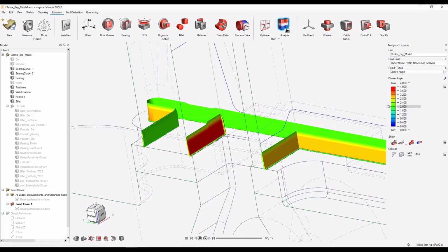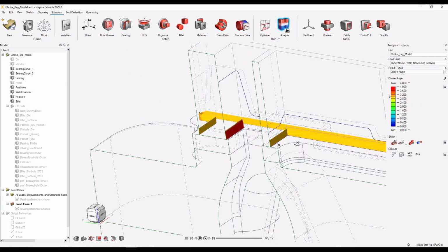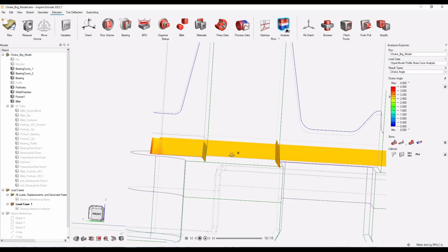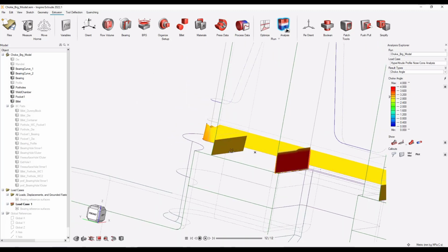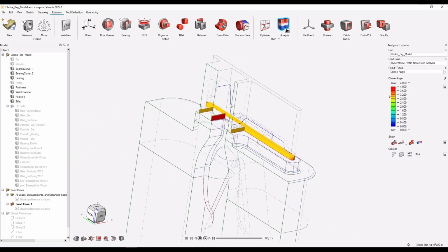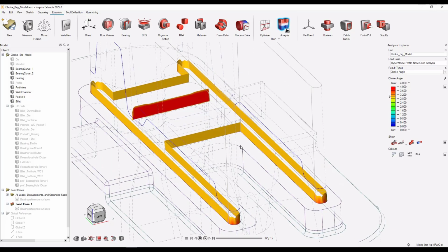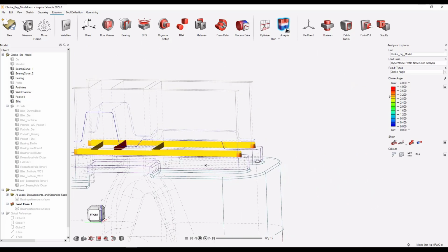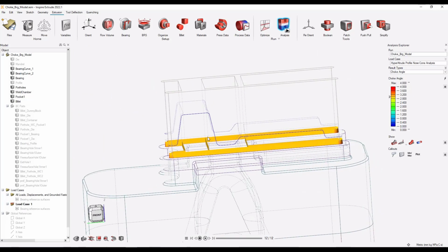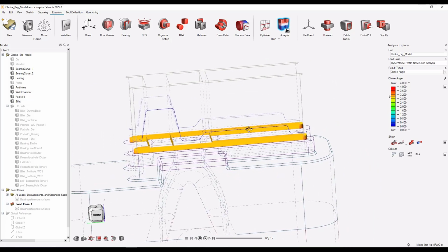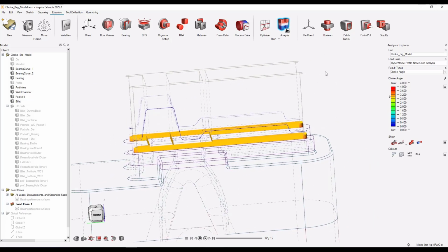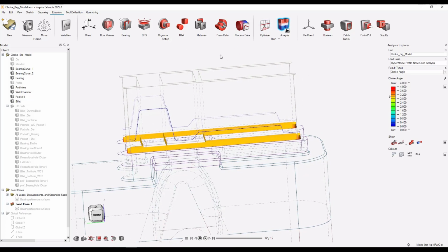Let's try changing it to, let's say, 3 degrees. So these are the choke angles with 3 degrees, and this is the choke angle with 4 degrees, that you can see over here. If I just switch on this, you can see it has detected the choke angle properly. This way you can quickly check the choke angle results, and I hope it is clear how to set up an extrusion simulation with choke bearings using this PRS option. Thank you.